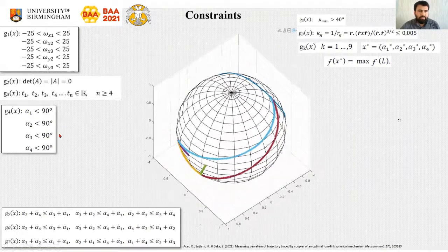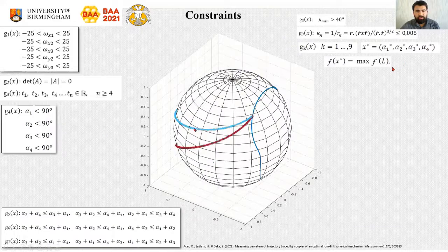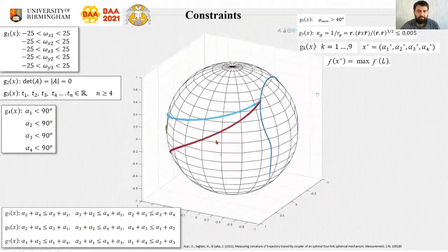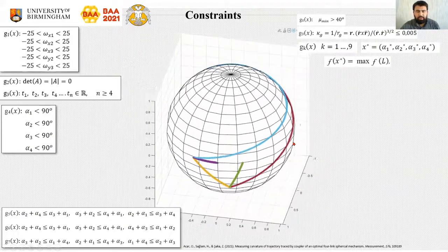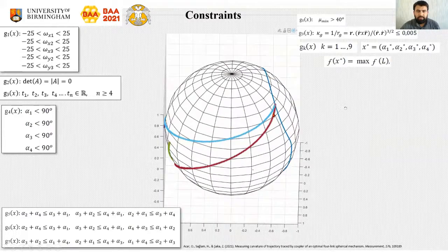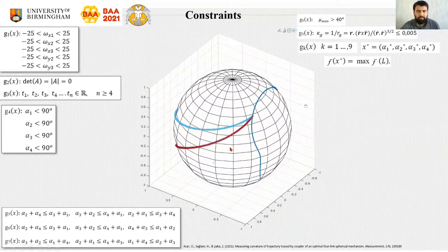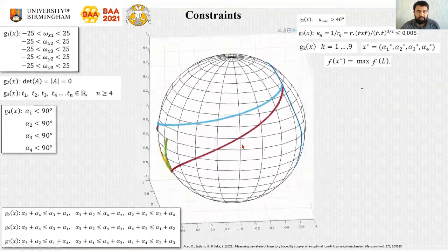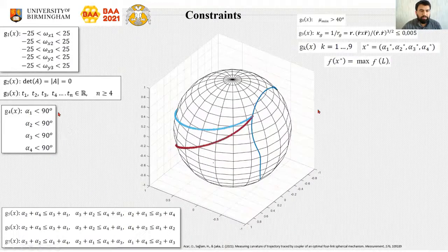Additionally, the link lengths are limited to 90 degrees to prevent similarity between the robotic fingers. As you can see here, there is a sample spherical four-bar mechanism which has links with higher dimensions than 90 degrees. This kind of spherical mechanism cannot be placed around a sphere symmetrically. We cannot design a three-fingered robotic gripper.